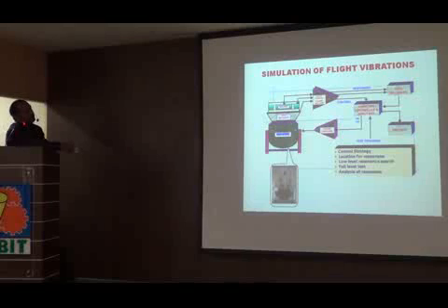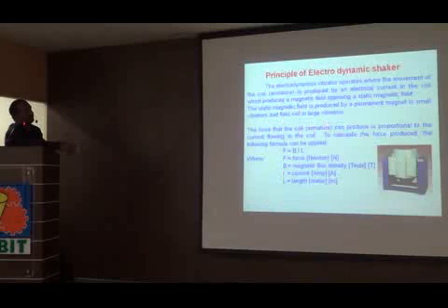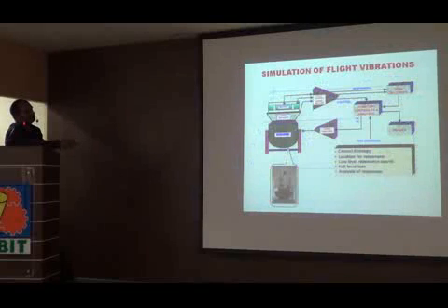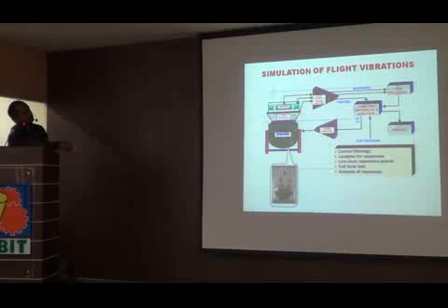So our role is that we need to control the input. You need to identify the locations where you need to put the sensors. You do a low level first, before the full level. When we say low level, what we mean is you initially give a low input and see the response, so that if there is any problem, you correct it and then go on. And then analyze all these responses. If there is any problem in the responses, then you need to modify the structure, design and change the structure accordingly, and try reducing the input, so that your systems are protected.